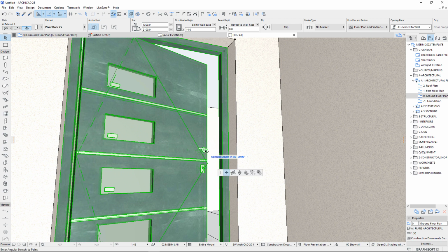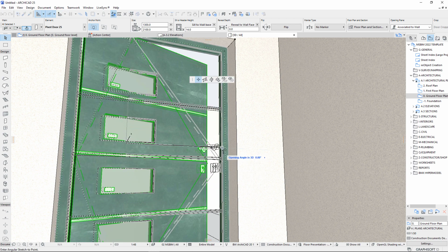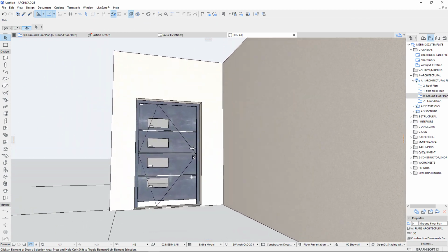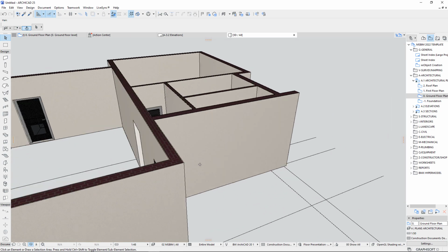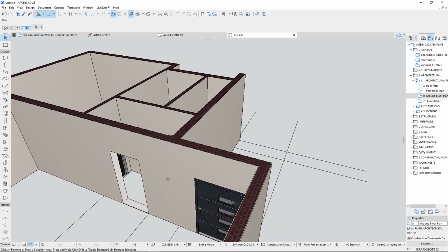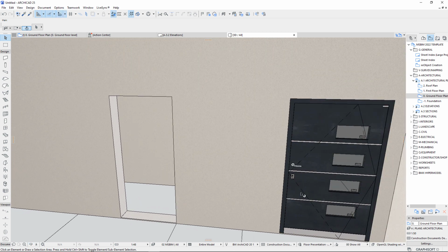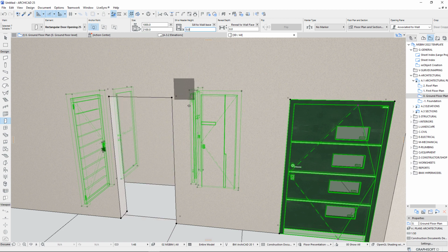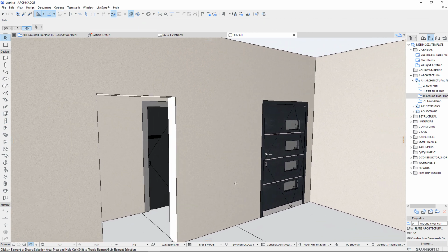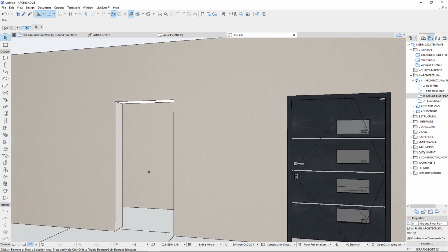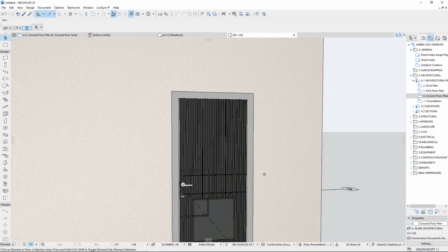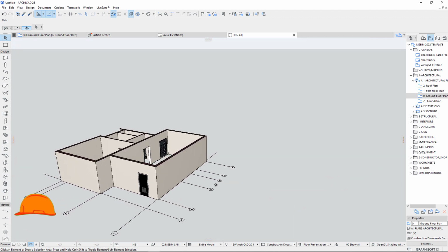We can close, this should be here. And then I'll make the 3D opening 0 just to keep it closed. As you can see, guys, I told you about this door. It's a very impressive door. Yeah, they come with this template. So I think now we need to set all our openings to an offset base of 0. So I'll Ctrl+A and select this and make the offset from the reference 0, so that it cleans up the whole thing like that. Perfect. Let's go to the fire door. Thank you. And everything is super, as you can see.